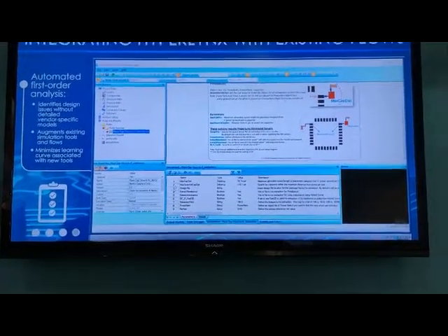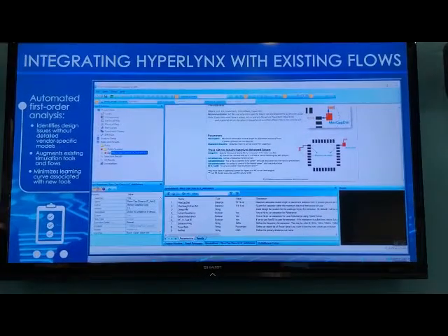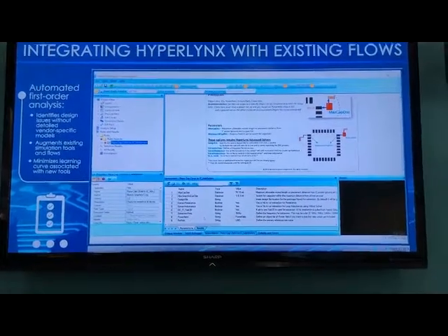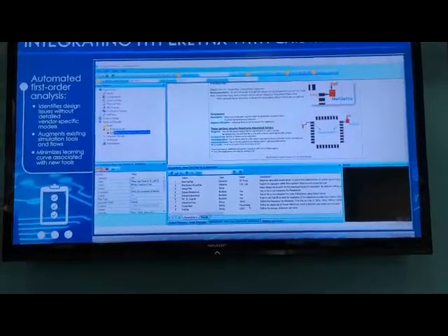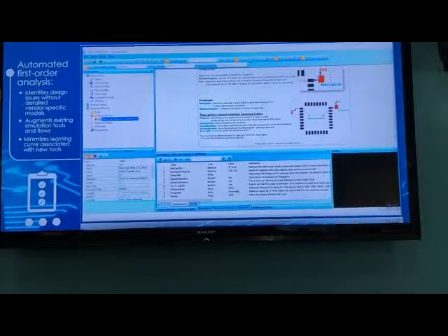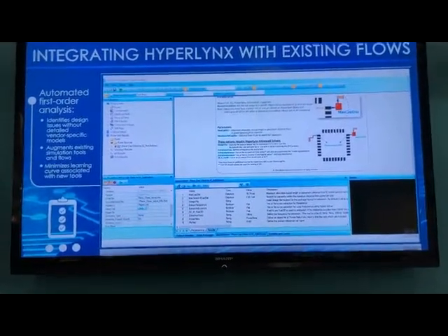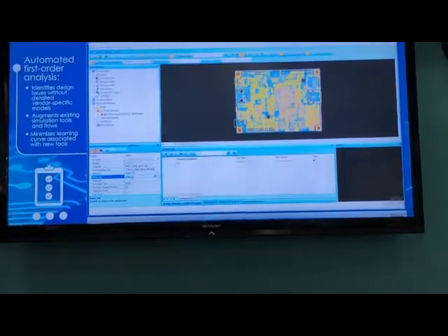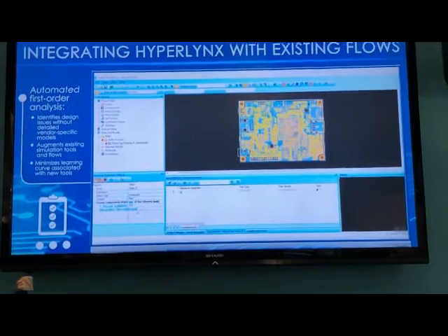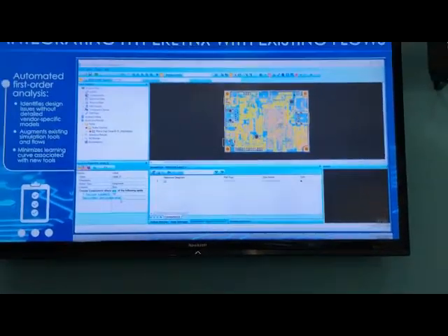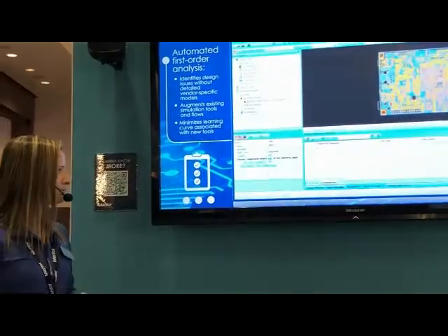And then I have some very simple parameters to set up the solver project file, what frequency I want to do the extraction for loop inductance. And the last thing I need to do is just give it a target list of ICs. But I don't want to go in and set that up every time, right? So I've got some nice filters that I'll show you here. In this case, I'm filtering on pin count, so it's automatically going to pull in my large ICs. But I could be filtering on schematic properties or anything that enables me to get this set up automatically.